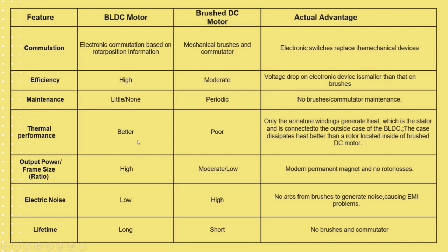Thermal performance is better because, as I said before, there are no brushes. Output power is high, and electric noise is low because there are no brushes. Lifetime is high because there are no brushes.